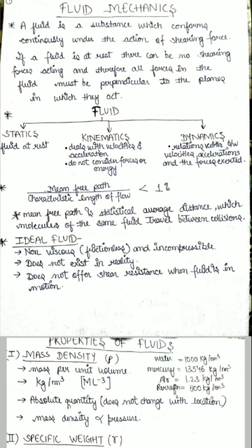Today, we'll be reading about fluid mechanics. A fluid is a substance which deforms continuously under the action of shearing force. If a fluid is at rest, there can be no shearing force acting, and therefore, all forces in the fluid must be perpendicular to the planes in which they act.